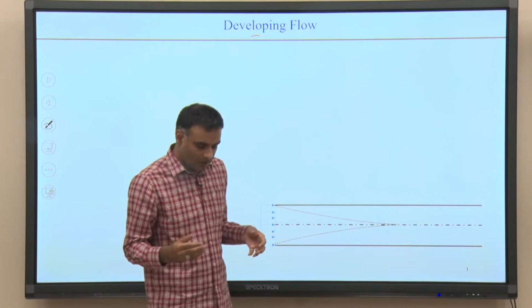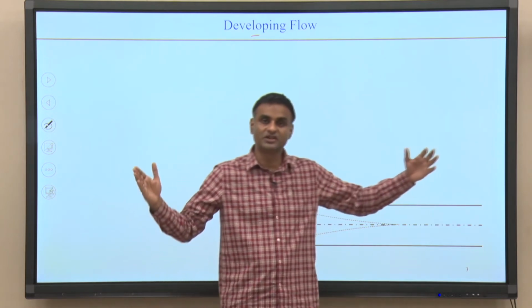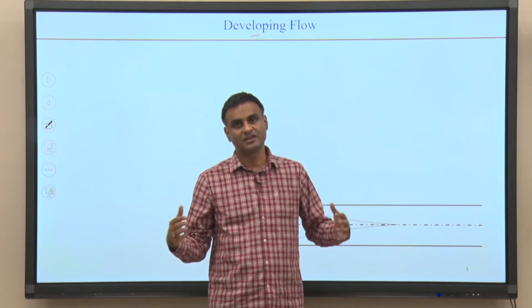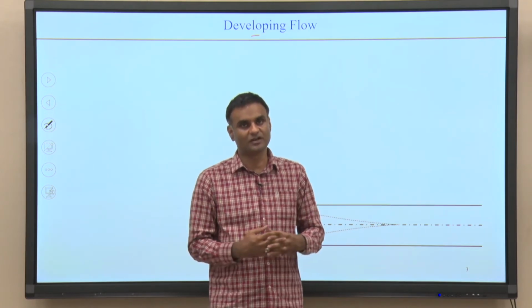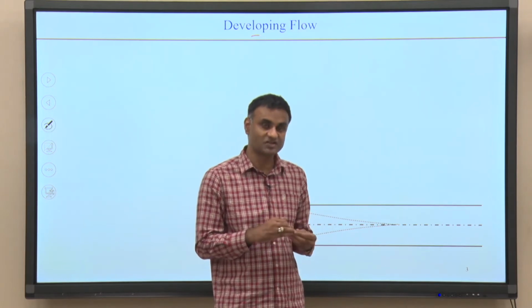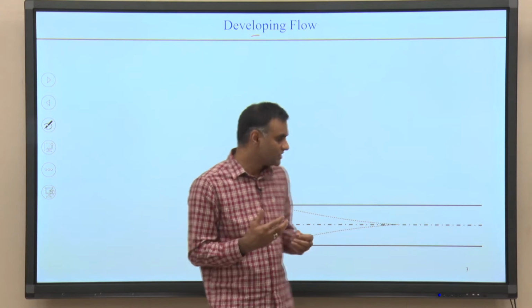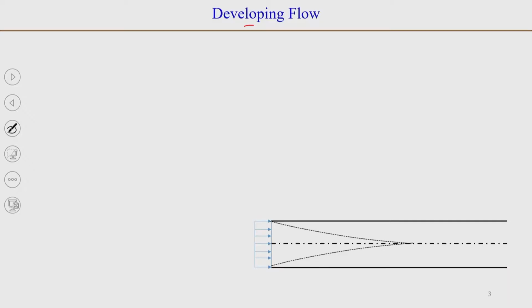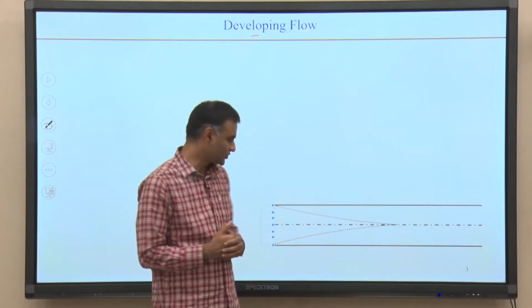Because the boundaries of the river are sufficiently far away, the velocity in the middle of the river will probably be turbulent in most cases, and when it is so, the velocity at the entrance of the pipe will be uniform. So, the flow enters with a uniform velocity.